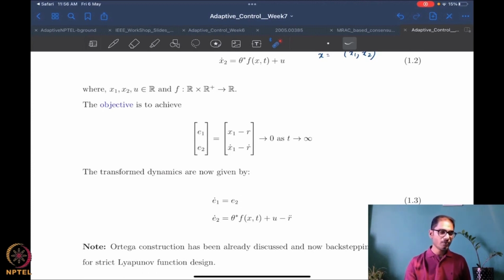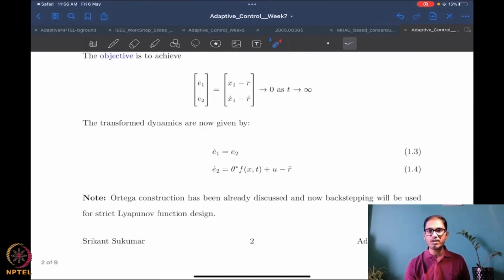All right. So what do we do next? We essentially derive the transformed dynamics. That is, now we have generated or created an error variable, and our aim is to, as always, drive these errors to zero, right? And so now, all this Lyapunov theory of considering the origin to be the equilibrium point, it all should start to make sense to all of you by now.